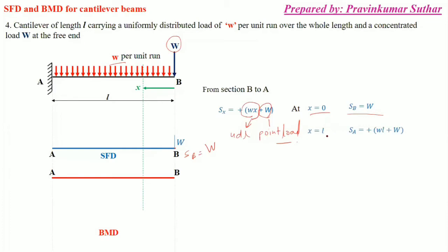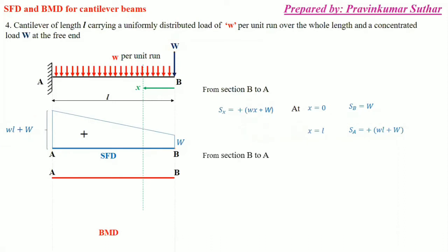At x equal to L, the value of shear force will be equal to wL plus W. So this is the maximum shear force because of both the UDL and the point load: wL plus W.